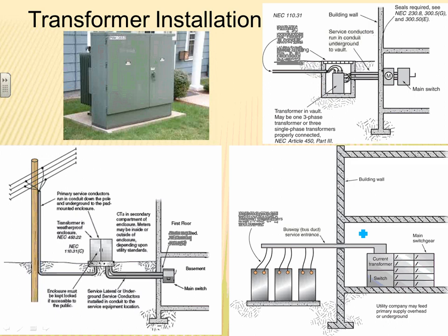So they powered hundreds of hospitals, and they can tell if it's a hospital, here is what an average hospital will take, this amount of power. Because of this, then they require you to have a termination box, long story short. So what you do is you come from here, from your transformer into your termination box. Now you size your termination box, you size this one to fit your own multiple feeders, and it goes into your building.